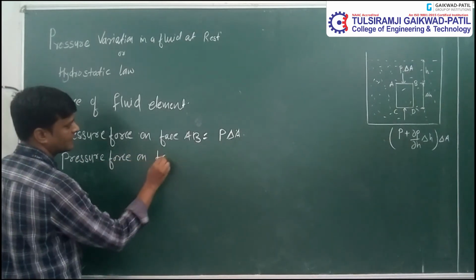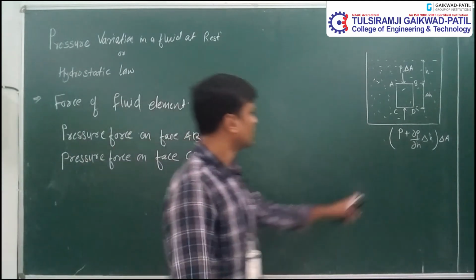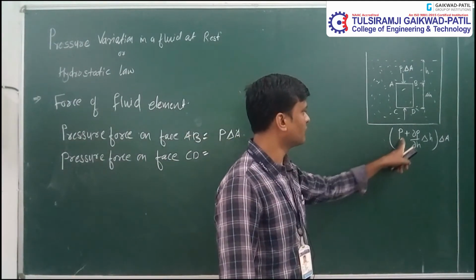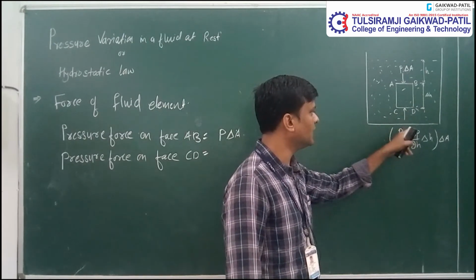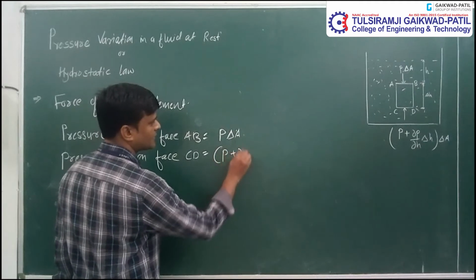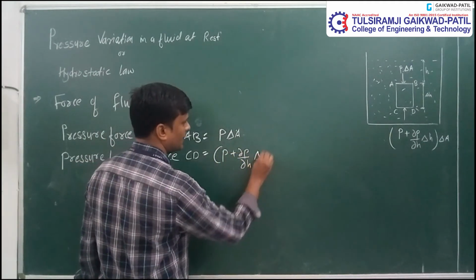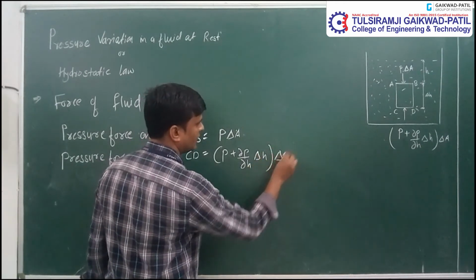Now, the pressure force on face CD. What is this? It is the pressure force which is acting on the face CD in the vertically upward direction. How much? P plus del P upon del H into delta H into delta A.